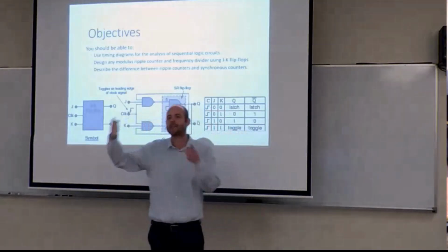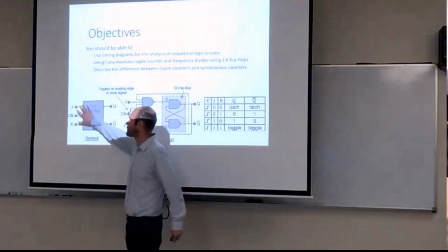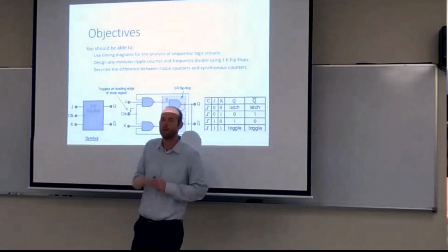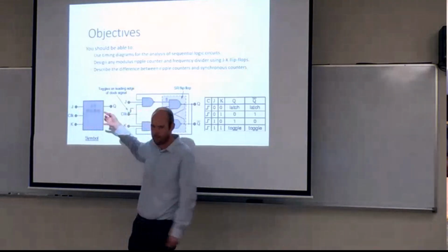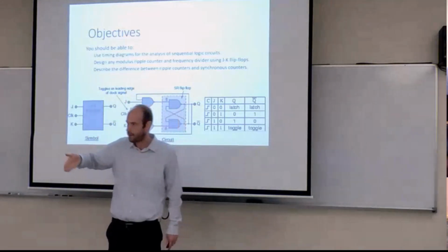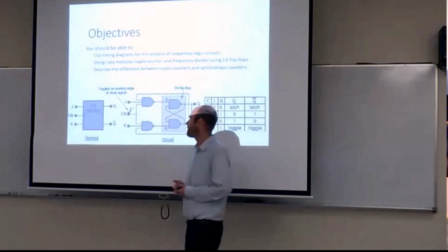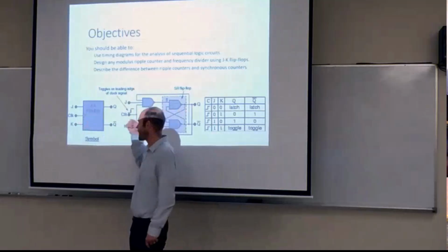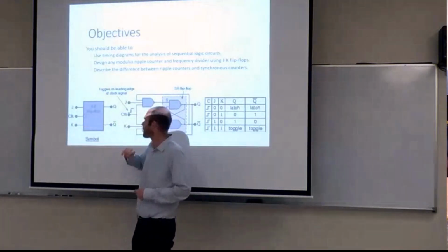Synchronous. It is in sync with the clock edge. It's a synchronous input, meaning we can set up J and K and toggle, change those bits, hit the buttons, flip whatever we want. The effect is only going to pass through the unit at the edge of the clock, when the edge of the clock strikes. And we'll see this in a lot of the homework when we build out timing diagrams. So at the edge of the clock is where the effect happens. That's referred to as a synchronous input.